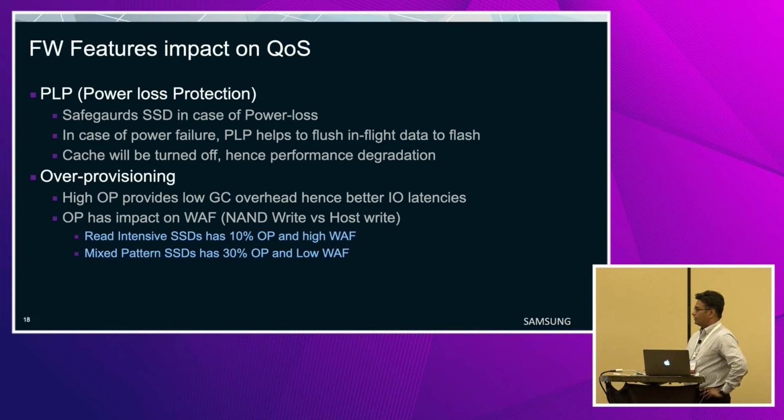Provisioning, we have already talked about this. One point I want to make: OP has an impact on WAF, write amplification factor. If there are read intensive SSDs, they normally have a 10% OP and a high write amplification factor. For mixed pattern SSDs, it is around 30%, on the higher side of over provisioning. Since OP is high, your WAF value will be low.